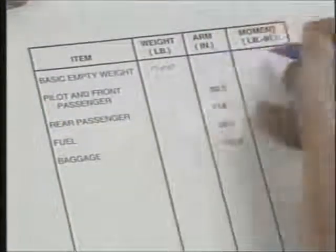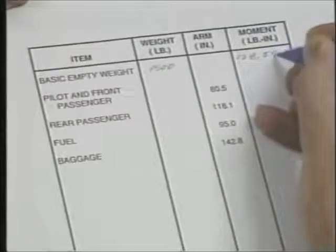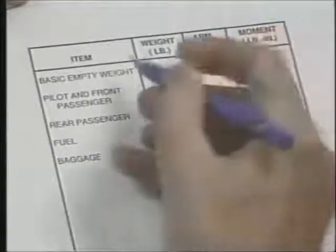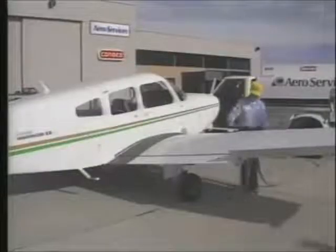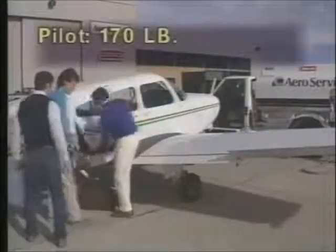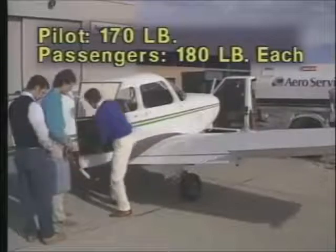This weight and its moment, along with its CG if given, is then transferred to a worksheet which contains 4 columns labeled as shown. You must then complete the weights and moments for the rest of the useful load. As a sample problem, assume you weigh 170 pounds and you're going to be carrying 2 passengers who each weigh 180 pounds.